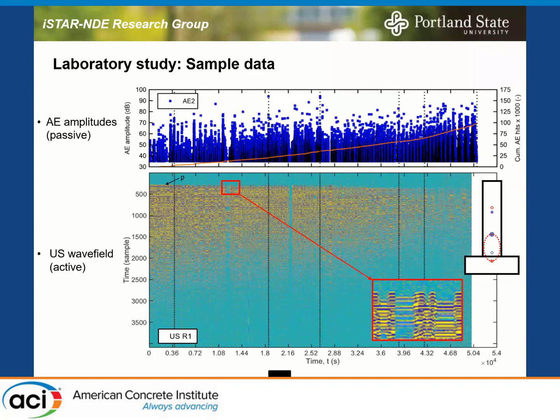I think by UPV you mean ultrasonic pulse velocity. Pulse velocity, right, yeah. Yeah, we can see that. If you think back to that plot where I lined up the ultrasonic signals, you can see in the very beginning when there's no damage, early on, when you have sort of linear behavior and there's just a little bit of push-pull on the column, that doesn't affect the ultrasonic pulse velocity.